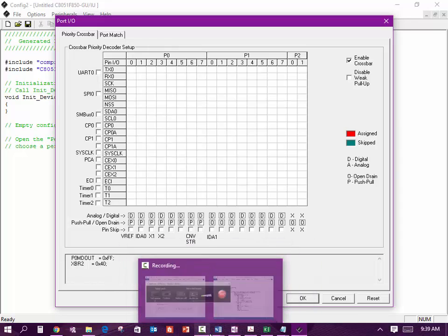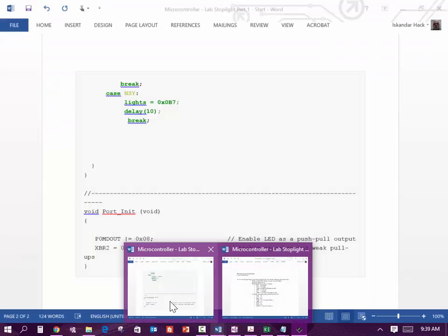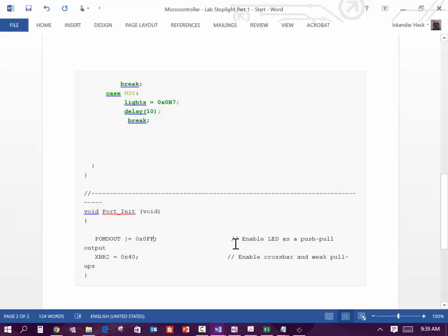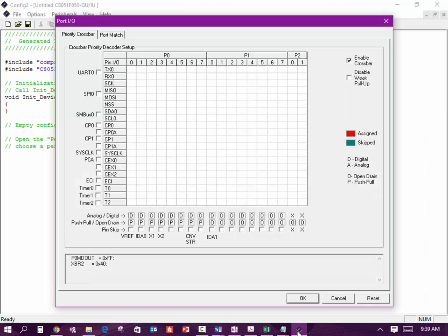Yeah, for whatever reason, I don't know why I put that there. I completely messed that up. And you can just simply go through and use that to set that up. But all I'm doing is telling it that those 8 bits are, when I said 0F, I was only doing the bottom 4 bits. I want to do all 8 bits, so it should be FF right there.